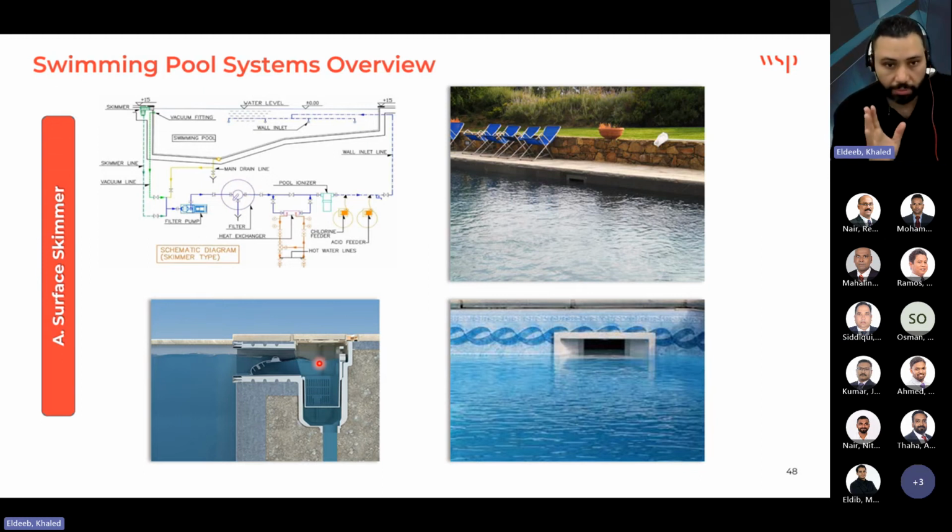Our course is totally for the swimming pool piping system. For an indoor pool, the only difference, you are right, is in the ventilation and the HVAC, but this is not covered. And this is the thing actually, nothing more. The temperature needs to be adjusted to a level higher than the water temperature of the pool to avoid condensation and extra evaporation.